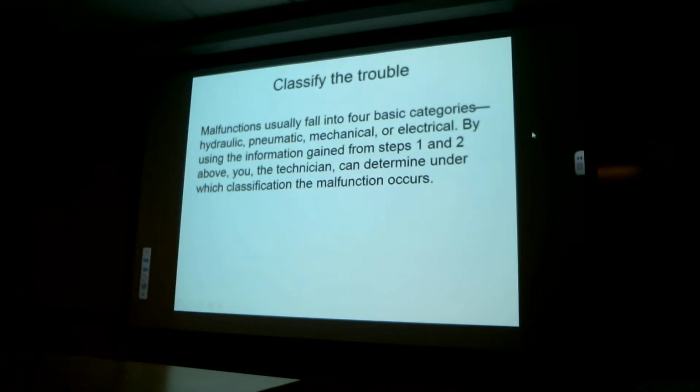Classify the trouble. Malfunctions usually fall into one of four basic categories: hydraulic, pneumatic, mechanical, or electrical. By using the information gained from steps 1 and 2 above, the technician can determine under which classification the malfunction occurs.